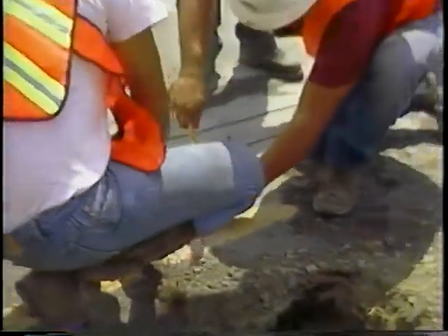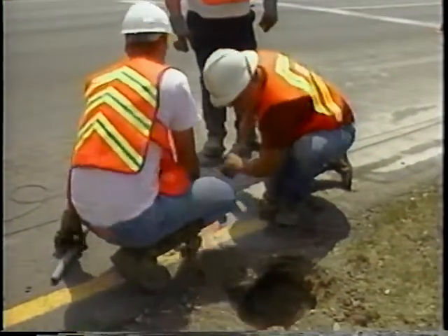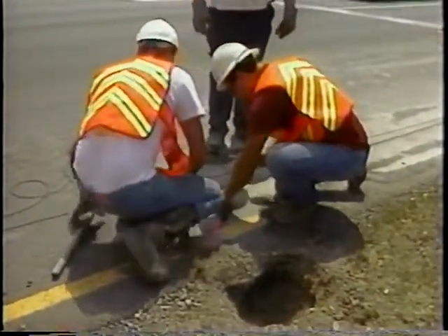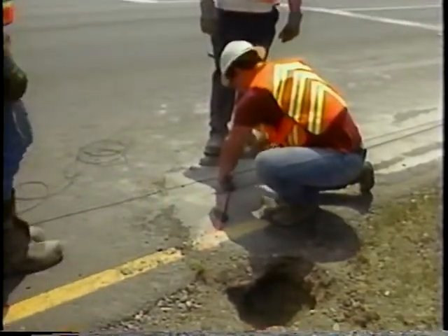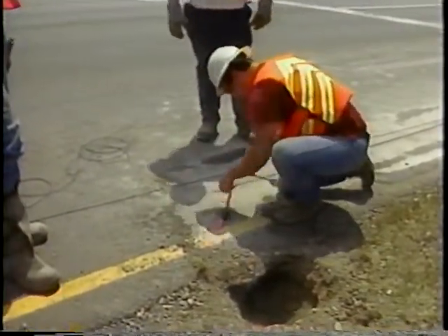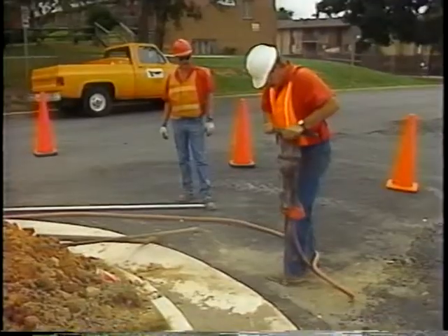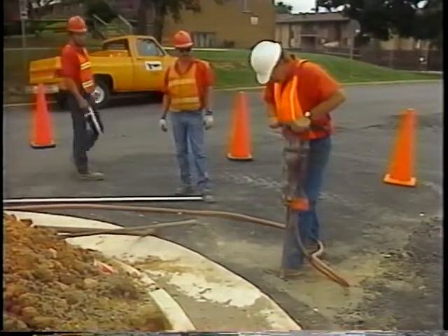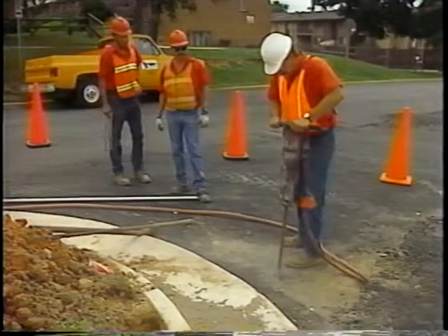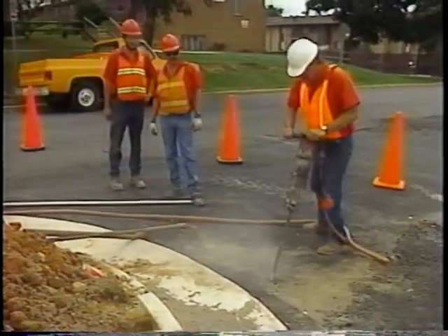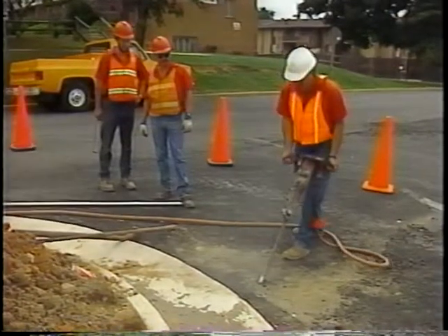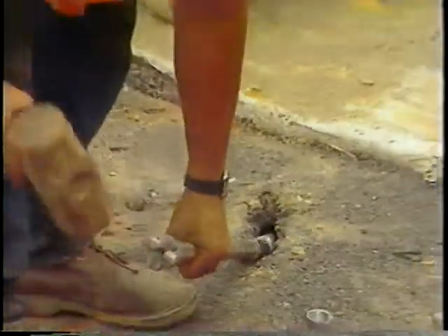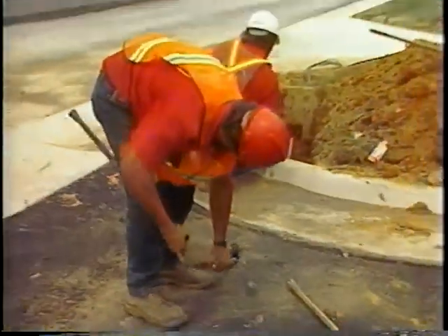Typically, the twisted lead-in wire extends from the loop across the curb or shoulder to the pull box. The lead-in wires from adjacent loops should be run to the pull box in separate slots to avoid crosstalk. At intersections with curbs, the joint where the road surface meets the curb line can cause problems for the twisted wire through horizontal and vertical shifting. Using a jackhammer drill or punch-type tool, make a hole in the curb and install a watertight, flexible conduit.